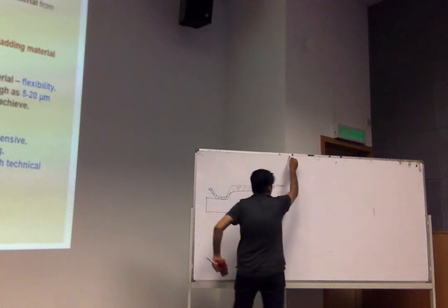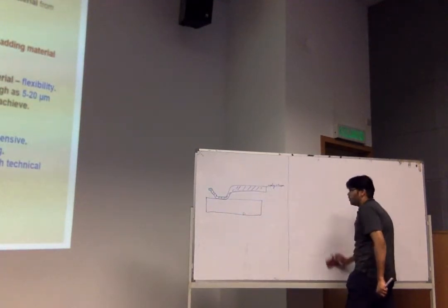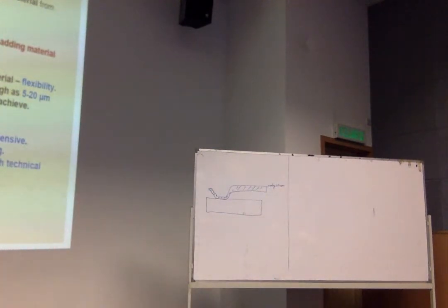If this is the one I want to achieve, then what could the surface micro machining steps be? So etching was bulk micro machining, that is removal of materials, so it's wasted. So surface micro machining is creating 3D structures by adding materials one on top of the other. So it involves, here also, some etching could be there, and also there could be some deposition as well. The thing is, it requires multiple masks and requires a sacrificial layer to create cavities.